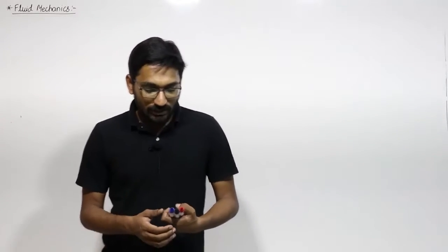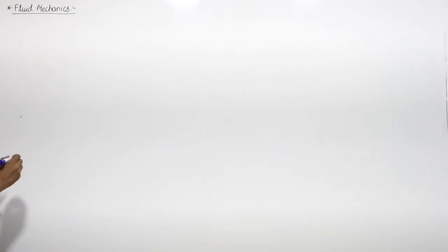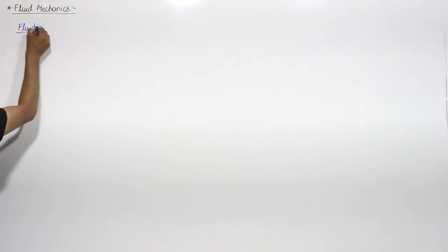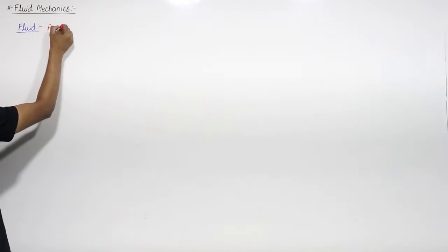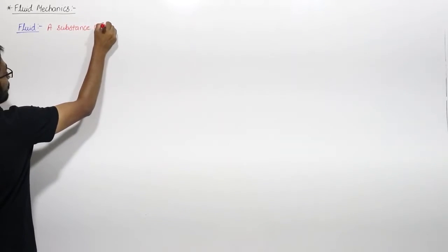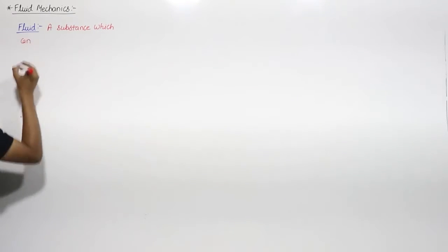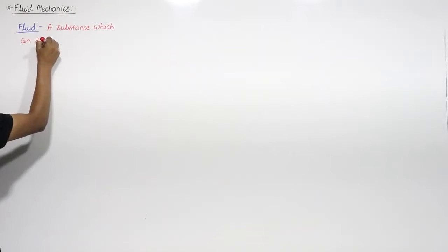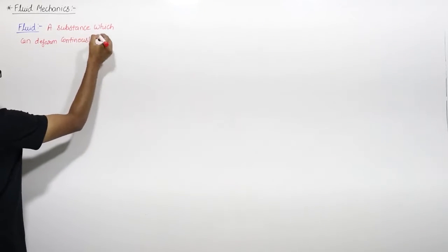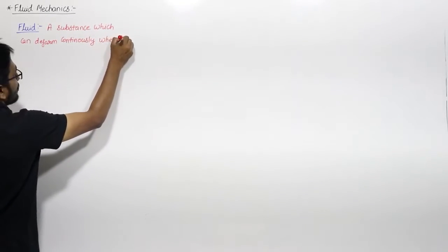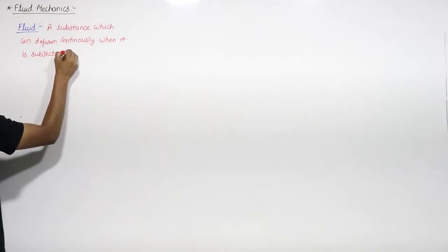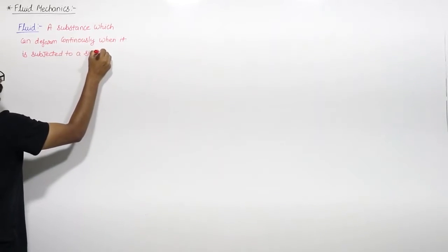Now let us start with the basic definition of fluid. If I write here, what do we mean by fluid? Fluid is a substance. If I write the definition, fluid is a substance which can deform continuously. This is important. Which can deform continuously when it is subjected to a shear stress or a shear force,